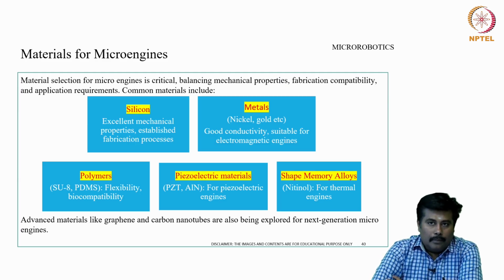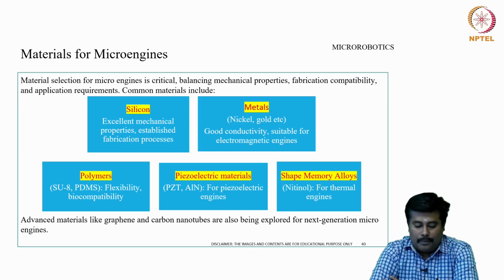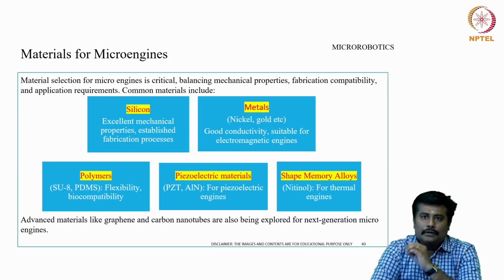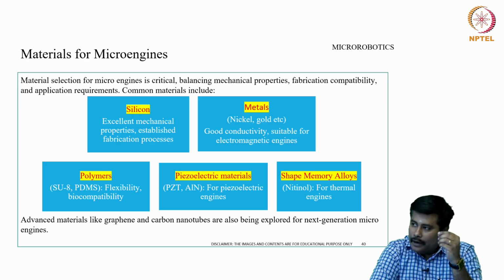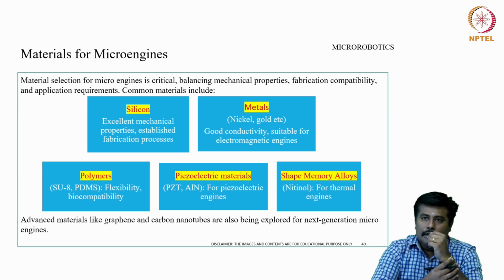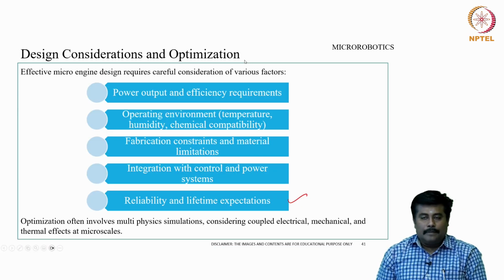From a polymer point of view, we have SU8 and PDMS structures, which offer flexibility and biocompatibility. From a piezoelectric point of view, there is a wide variety of materials which exhibit piezoelectric capability. Recently, lead free zinc oxides have also been efficiently used for piezoelectric related applications, and there are certain shape memory alloy materials which are also being exhibited.